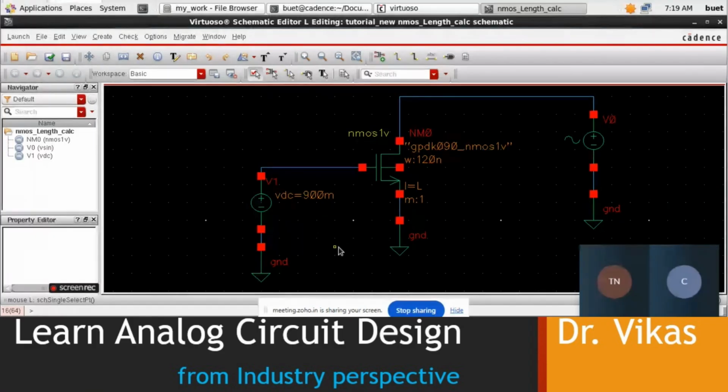To ensure that, I am attaching a current source. I cannot use the normal current sources like IDC or ISine in building my circuit, because when it goes for fabrication, you cannot always use the typical current sources since those are bigger in size. So you need to develop some current sources using the MOSFETs only. And there comes the concept of current mirror. Current mirrors or current sources, their job is to ensure whatever the reference current is, they will be mirroring those currents. So in order to generate the current source, I need to first build the current mirror. And in order to do all that, I need to establish certain conditions.